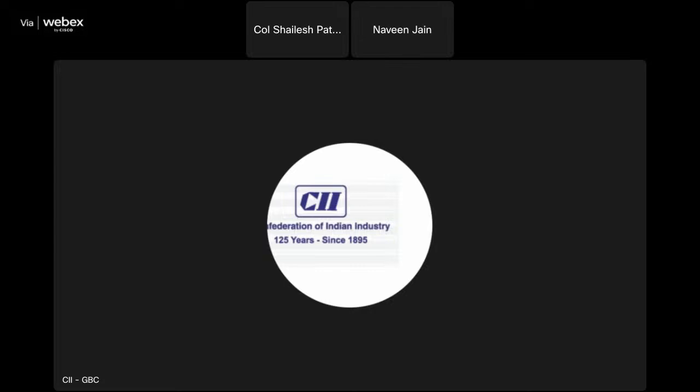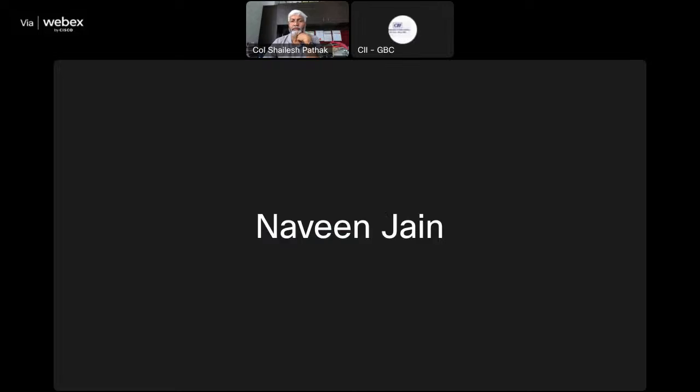I think the solar efficiency question. Right now, 20 to 23% solar cell efficiency is there. Even for solar cells, it is more than 24%. But when it comes to the module, it is 20 to 23%. I'll talk about mono PERC, which is one technology of cells. They have 20 to 23% efficiency. Solar cells have higher efficiency. If a solar cell has 24 or 25%, then when it comes into the module combination, the efficiency reduces by 1 or 2%, and it becomes 20 to 23%.